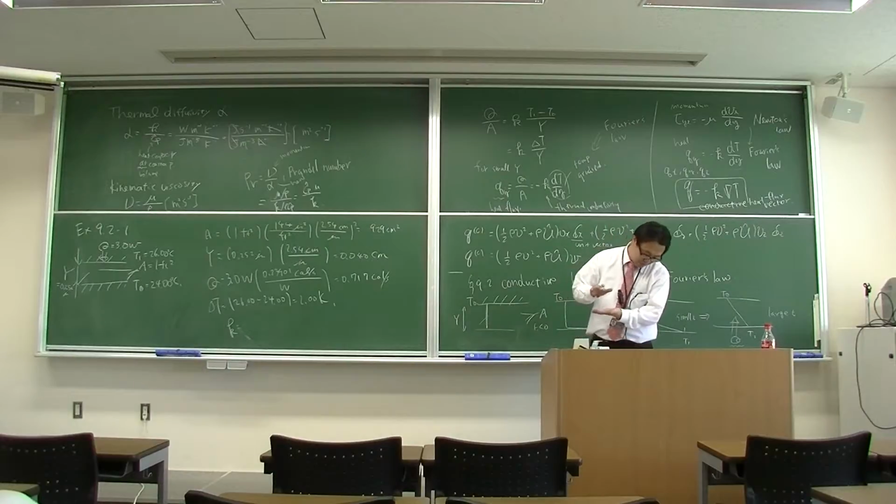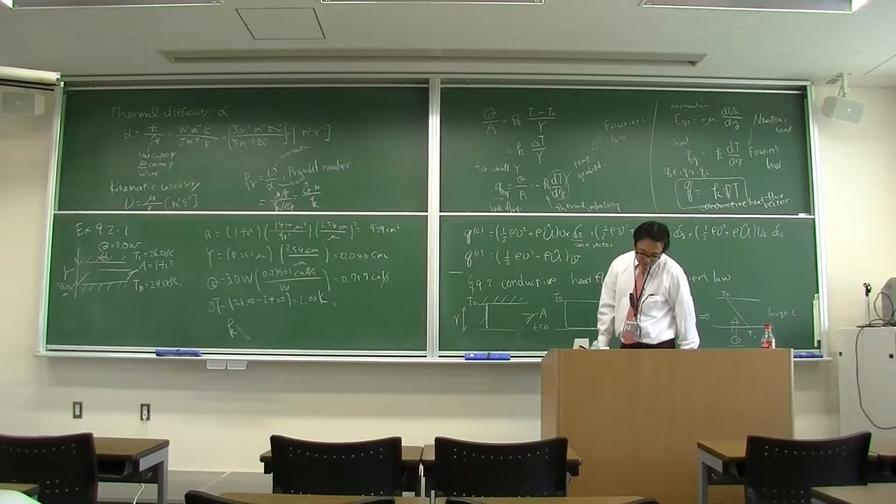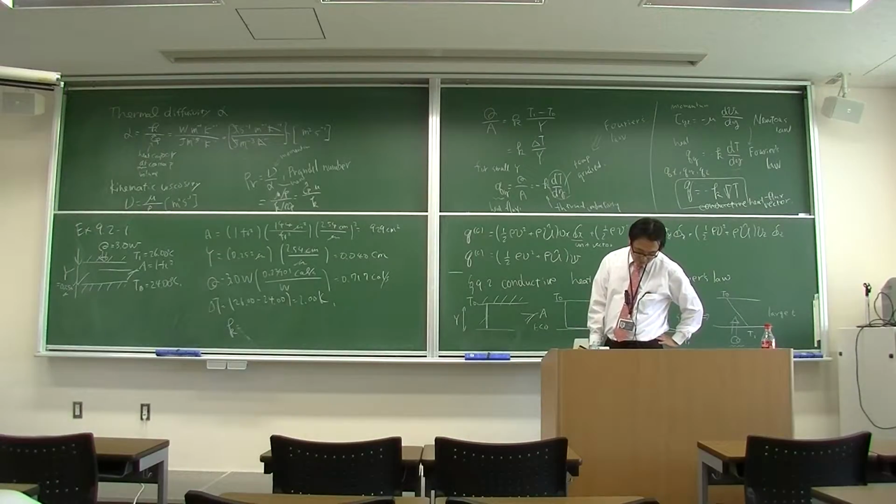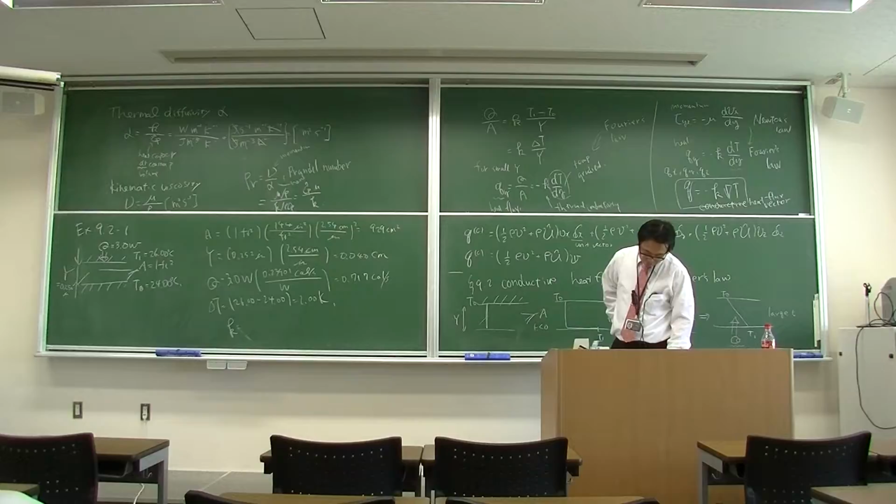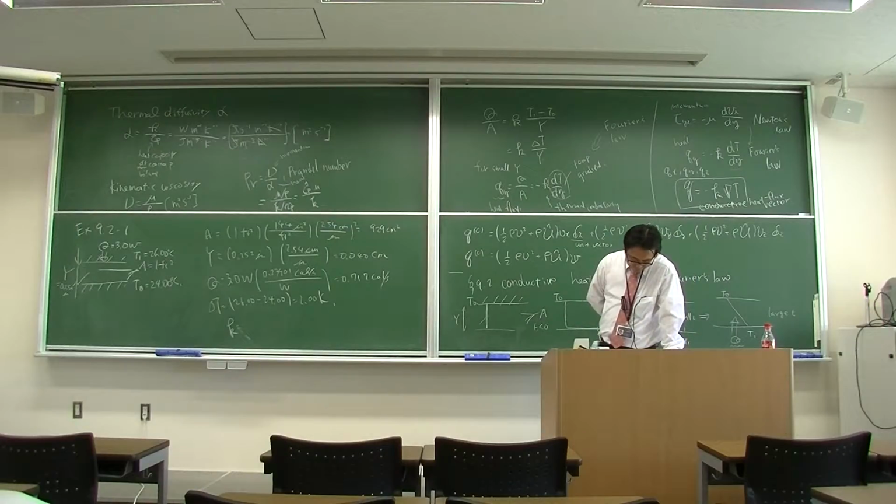A plastic panel of area equal 1 square feet, and thickness y equal 0.252 inch was found to conduct heat at a rate of 2.10 watt at a steady state with temperature T0 24 degrees C and T1 26 degrees C imposed on the two main surfaces.